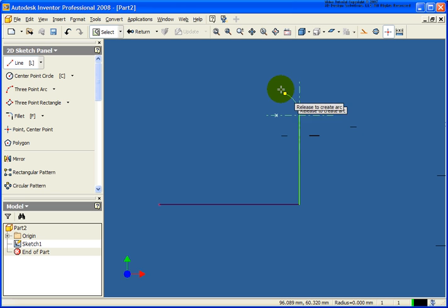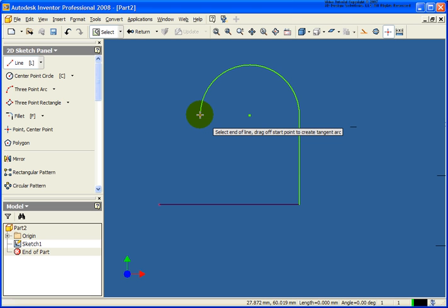So I'm going to kind of go back to where I was in the very first place. And as I'm sketching, you'll notice that I'm also getting these dotted lines. Those are referred to as inferred points. So it's basically telling me in this case, if I select that point right there, it will be positioned to the left or horizontally to that last point. However, what that will not be doing is applying a constraint. So I could go back and drag that later.